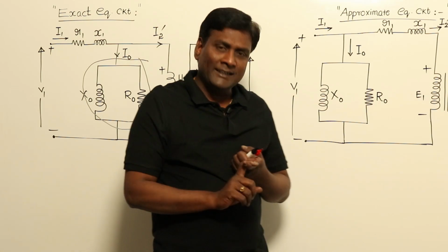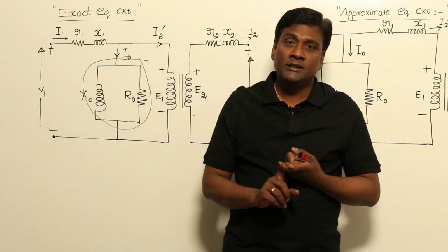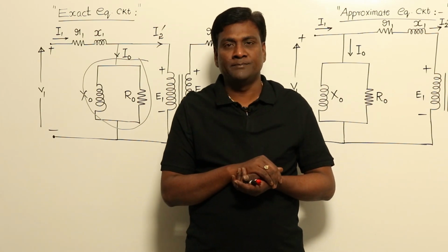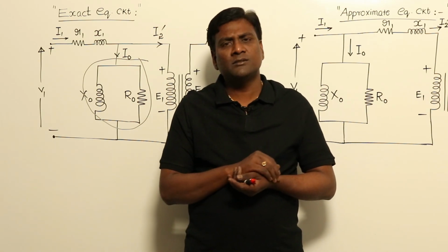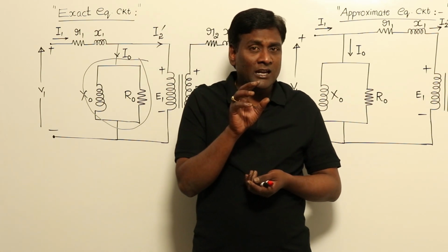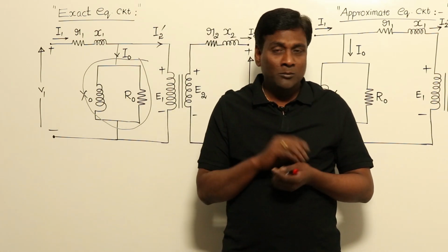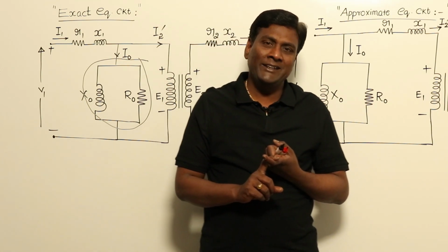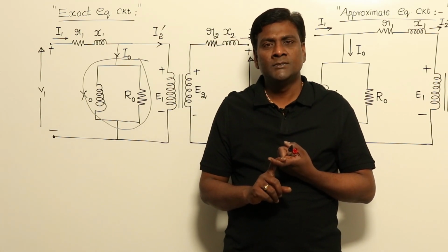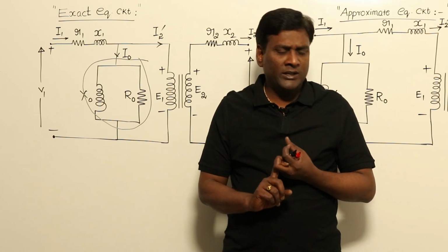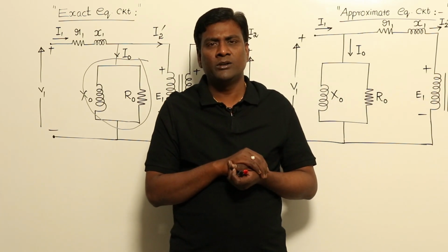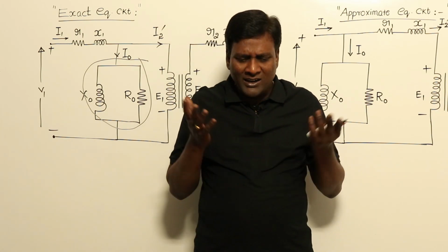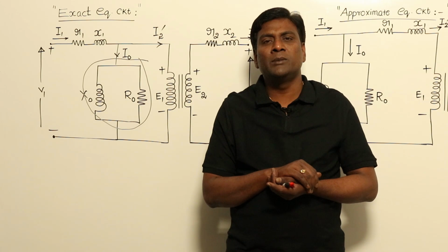Leakage will influence all terminal response characteristics except efficiency, because leakage is lossless. In efficiency calculations we need not bother about leakage, but voltage regulation will be influenced by leakage. That's why we are modeling leakage. And maybe if you think of an induction motor, maximum torque or pull out torque will be influenced by leakage, or power handling capacity of the machine will be decided by leakage.